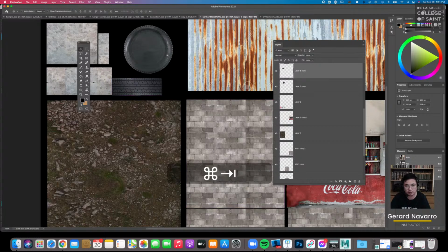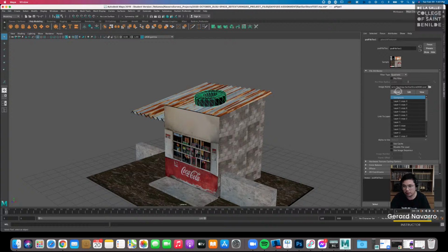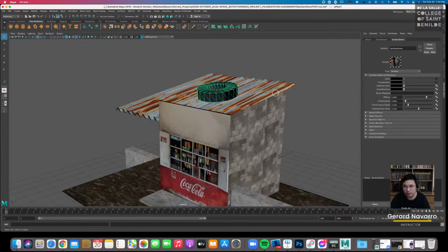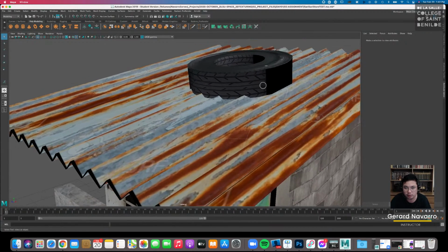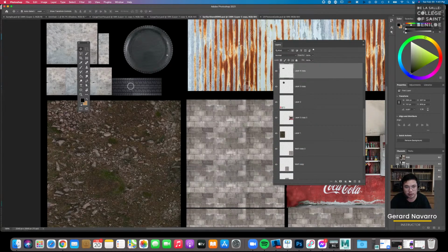So, if I save this, and then let's select our object, then reload, there it is. Oops. So again, the transparency comes back. That's the problem with PSD. I think there's a bug in Maya. But yes, every time you reload your textures, it reapplies the connection to transparency. So you need to break it again to fix it. So, you can see, it looks better like that, squished, compared to earlier. So what you need to do now is duplicate this one a little bit more.